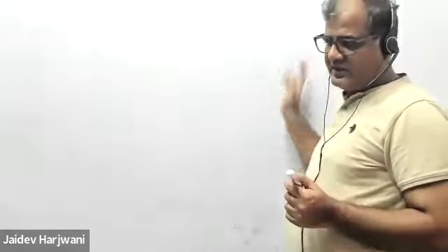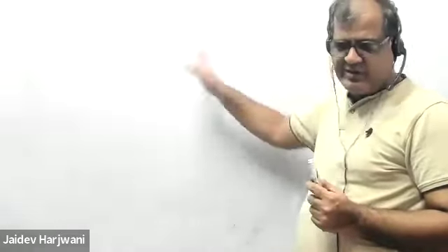Sir, I didn't get it. See, just now we have made an op-amp oscillator. We have not done the transistor, but we have done the op-amp as an oscillator. It's continuously producing a square wave without any input. We are using it in inverting configuration. Yes or no? Yes, sir. Inverting configuration means there should be a phase difference of how much? 180. So here one RC section is producing a phase difference of 30. If you give this RC as an input to a transistor, how many do you require? 6, right?